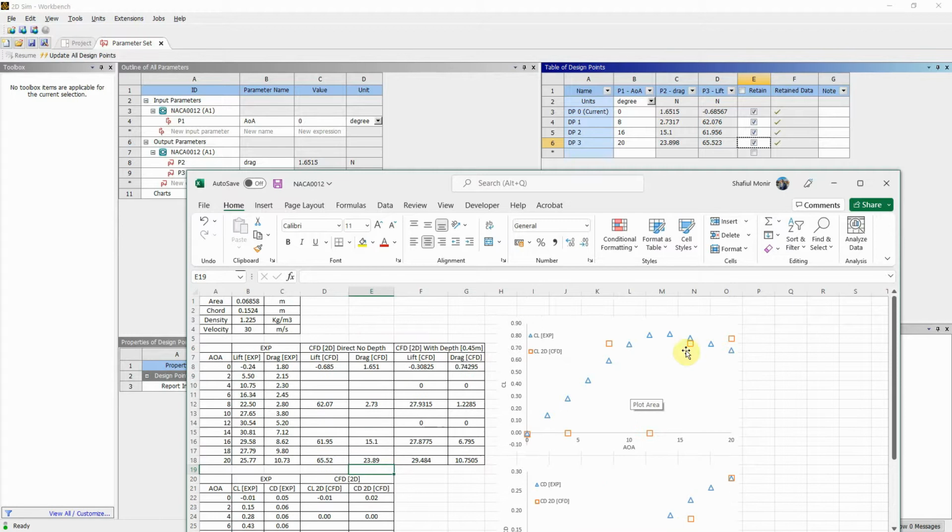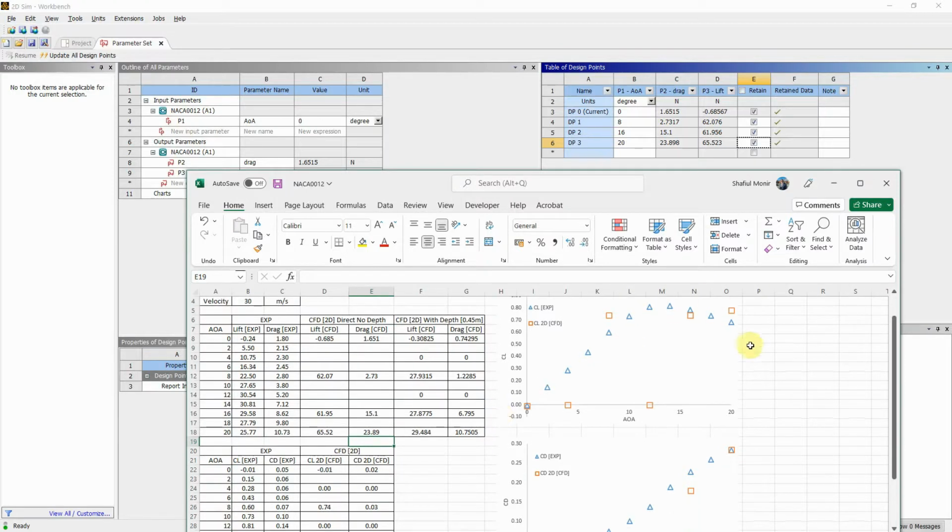The one good thing is that there is a stalling angle taking place. But you can get it a lot closer by maybe looking at the turbulence model, maybe looking at the mesh, to see what effect it has. If you are doing a mesh dependency or a turbulence dependency study, I wouldn't do it for all the angles. I would just do it for the 4.